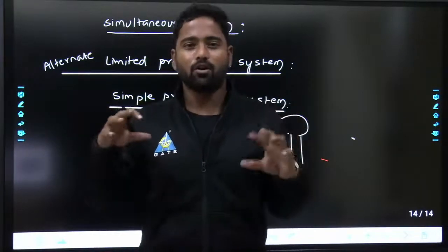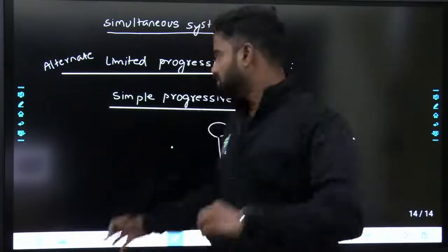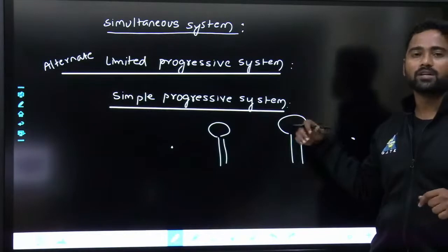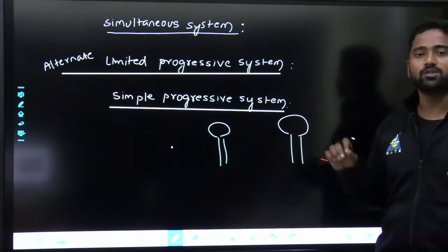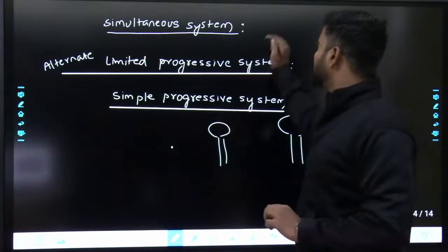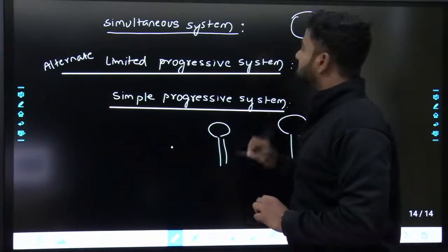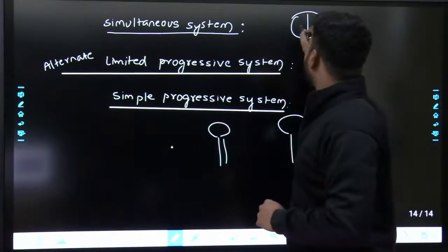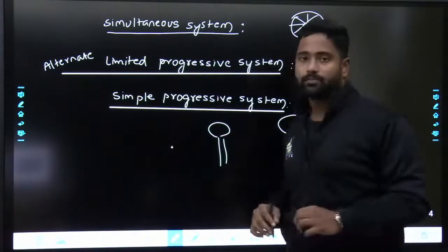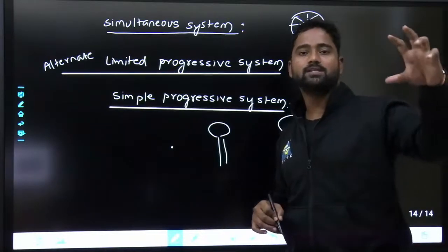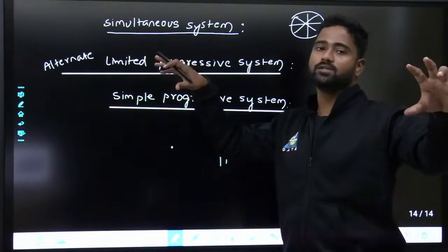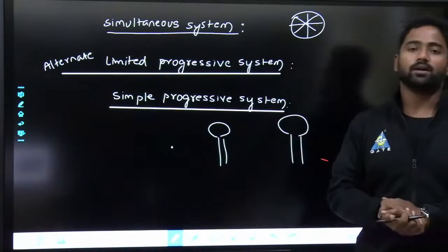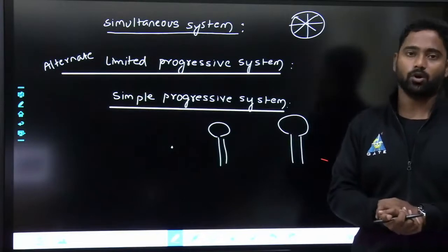We do not consider vehicles moving from one point to another or whether there will be delay. We design it so that all the systems have the same cycle length, so that if green is 60 seconds in one direction, it will be 60 seconds in the other direction, and all the vehicles leave the intersection in the given time period.